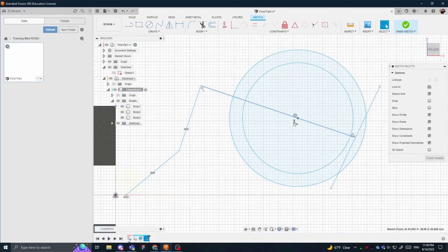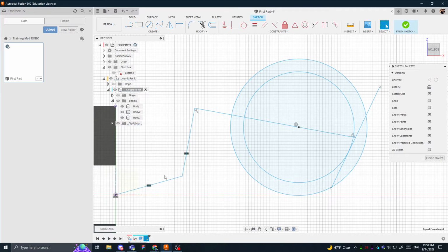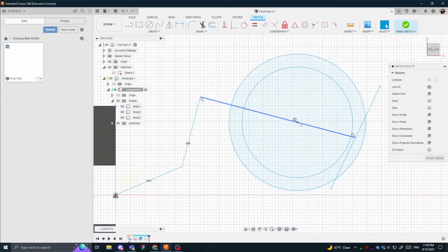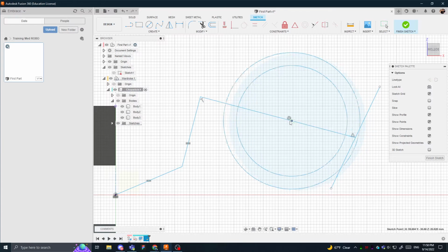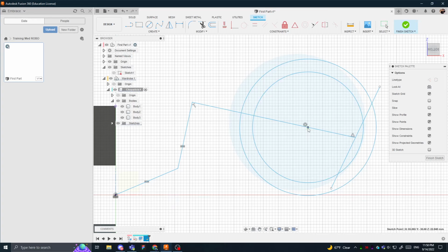This is really useful to know what each of these symbols are, so you can immediately know that's locked to the middle. This one means that these two circles are locked together. This is perpendicular, that's parallel. I mean, not parallel, equal. So this always stays the same length to each other. This always has to stay horizontal. If I drag it over the center point here, and I say coincident, then it's always locked to the origin point. And I deleted the midpoint because technically the midpoint is right here. However, I don't want it there because I want it here.